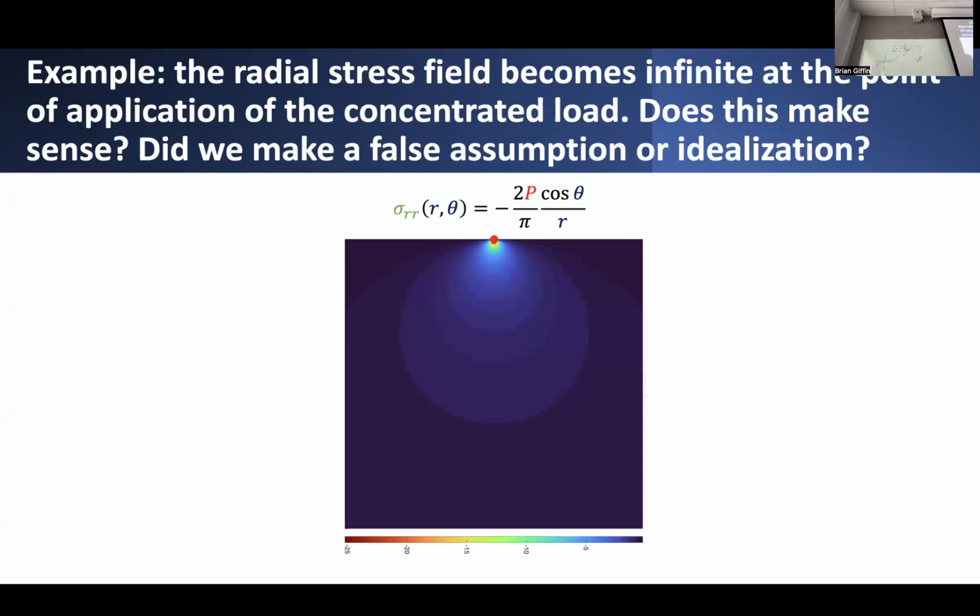But further away from the loading, as I go further and further down, some of your intuition comes to bear on understanding what's actually going on in this problem. Certainly, further away, the stresses start to distribute out. So if we looked at what's the stress along some kind of cut plane below the surface of that point of application, now the stresses die off actually quite quickly.